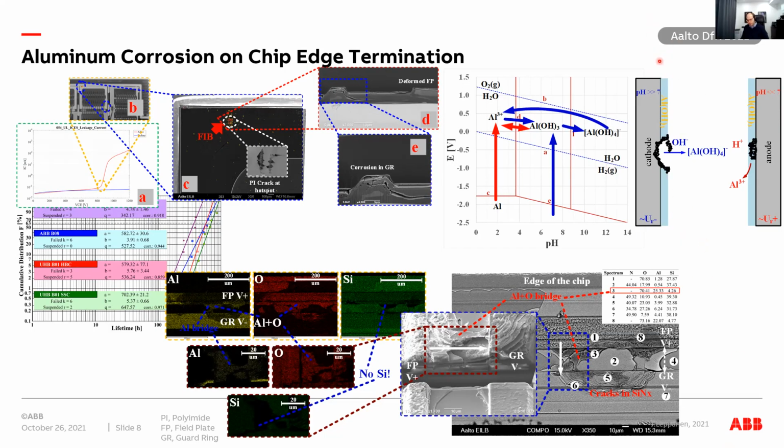So we start biasing the voltage only shortly after we have reached the conditions. So maybe already some of the humidity has penetrated the package and the chip at that time, and then we start having this aluminum hydroxide there already. But nevertheless, it will eventually form also, even with the voltage, on the surfaces.